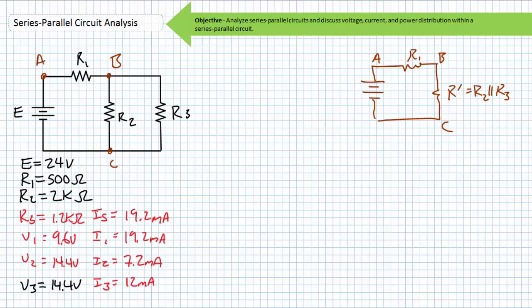Visualize the circuit at the nodal level and from the perspective of flowing current. Current in a single path is the same. Voltage across paths in parallel is the same. For every rise there is a drop, and what goes in must come out.